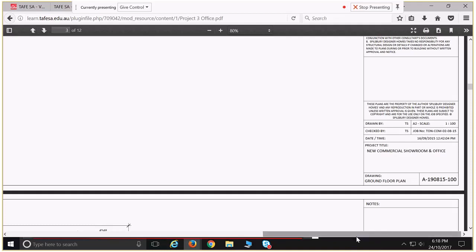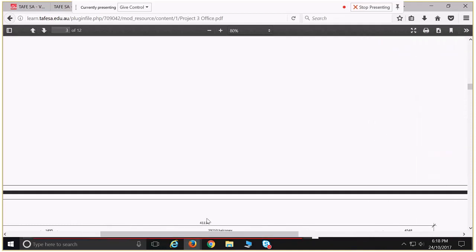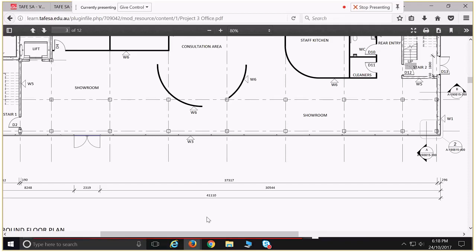That's not how I would do it myself, because that's only going to be legible on an A1 drawing, on a large scale. In fact, it's not all that legible. I prefer to number my pages D1, D2, D3, D4, D5, etc., so that's drawing 1, 2, 3, 4, 5 through to the end of the drawings. Then if I have any plan details, I will have those page numbers as PD1, PD2, PD3, and section details SD1, SD2, SD3, etc.